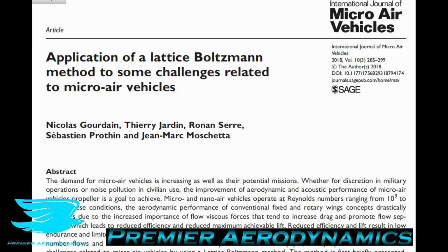So up until now, for the last 30 years at least, whenever someone said CFD, we always immediately think we're using Navier-Stokes equations. So we're using RANS, URANS, DES, LES, DNS. And that is for good reason. That is because the Navier-Stokes equations up until now have provided a very good method of simulating flow. They're far better in terms of accuracy compared to potential flow solvers or the elliptic line theory, which is very old but still quite a nice little tool if you know how to use it properly for certain applications. But CFD now is definitely dominated by Navier-Stokes equations.